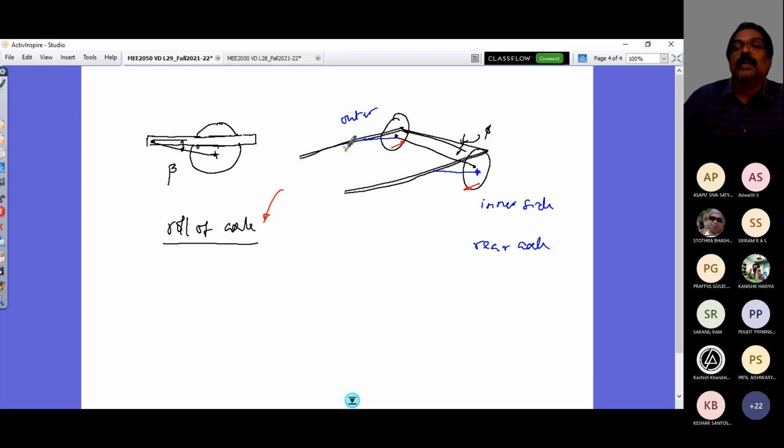It is going to contribute to oversteer tendency, because the vehicle already goes to this side, and this outer wheel pushes the vehicle to the inner side. So the effect would be an oversteer effect. If the initial orientation of the rear axle's trailing arm angle is downward here and going up here, the inner wheel is pushed forward and the outer wheel backward, which acts on the rear axle, right?